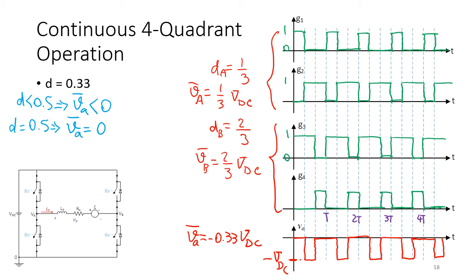So in this case, as you can see, you just see negative voltage and 0 in the negative voltage. In the case of the positive voltage, you saw just positive voltage and 0. That's why in some cases they call this way of switching, or PWM, unipolar PWM. You have just positive or negative and 0. You don't have both positive and negative.